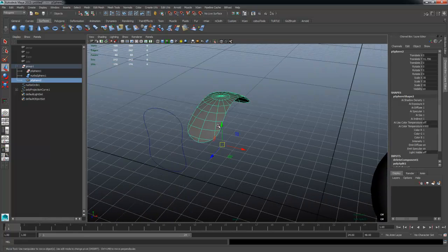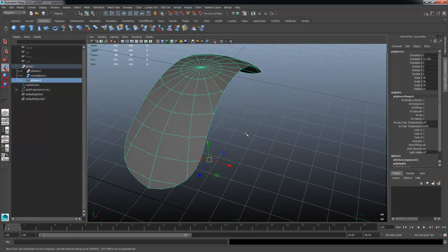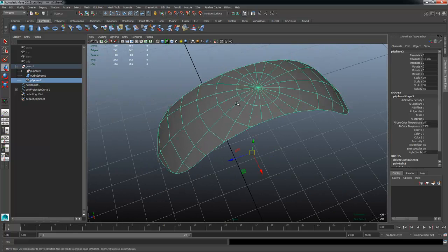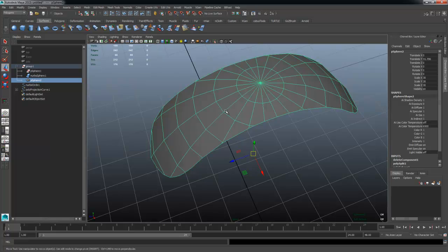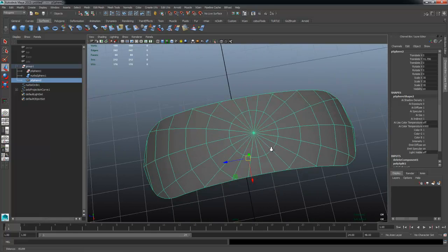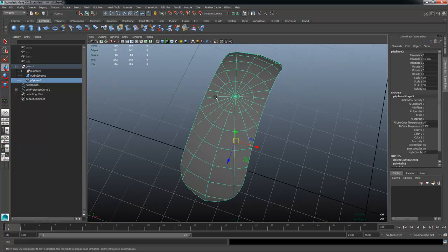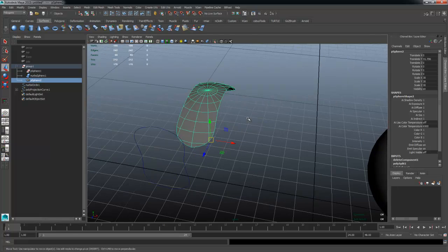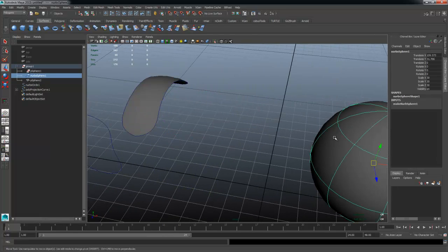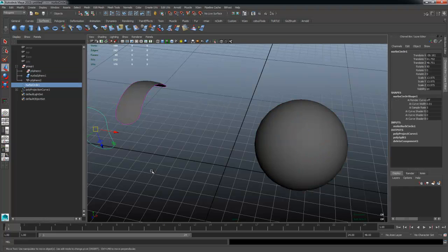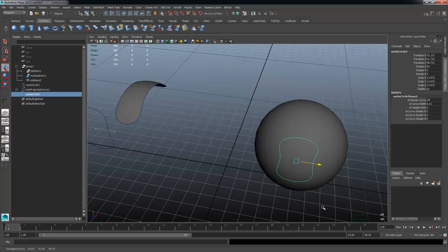This is my preferred method purely because I can then decide how I want to manipulate the polygon model afterwards. Yes, it does have the same original details on the surface. It's still making use of the same edges that the original sphere had, but I can obviously still go in and manipulate these edges, clean them up, and do whatever I need to, like giving it thickness and so on. But by all means, I have the ability to choose either the polygon method or the NURBS method, which I'm just going to redo again after my crash.